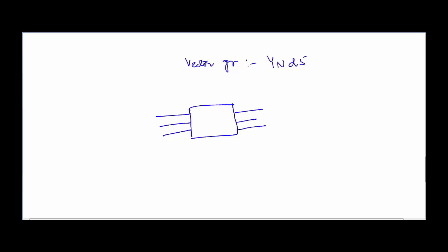On the nameplate of the transformer, we have an expression regarding the vector group of the transformer, and it will be written like YNd5. Now there is some meaning regarding this expression. Well, let us just suppose that we have a transformer, and this side is the HV side, and we are going to have three phases for that, and this side is the LT side, and we will be having three phases for that.